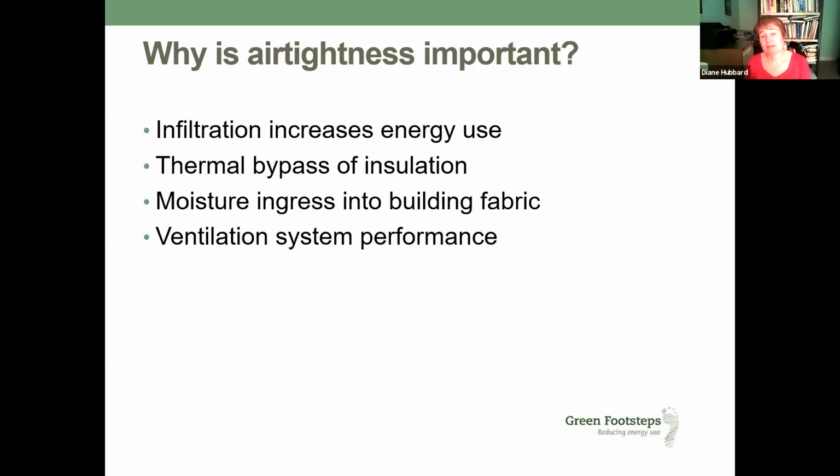Another thing to bear in mind is that air tightness could affect the performance of ventilation systems. Particularly where you're looking at mechanical ventilation with heat recovery, which is being put into an awful lot of retrofits, you may find that if the building is too leaky, there'll be two consequences. One is that the air movement that's planned really doesn't happen in reality.